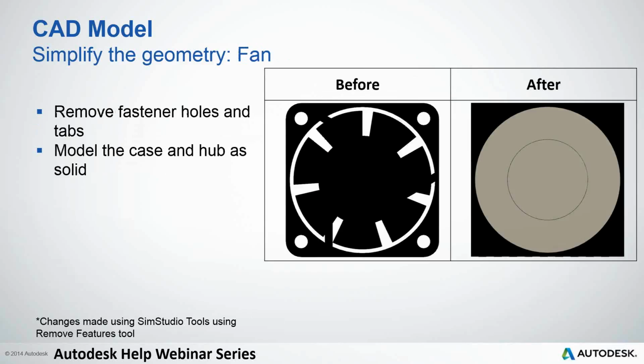So here we modeled a fan that was on the CAD model. Basically, I wanted to get rid of the actual blades and replace it with volume so I can use the internal fan material in CFD. So it's really useful to know ahead of time what kind of assumptions you're going to make and what your end goal is really here.